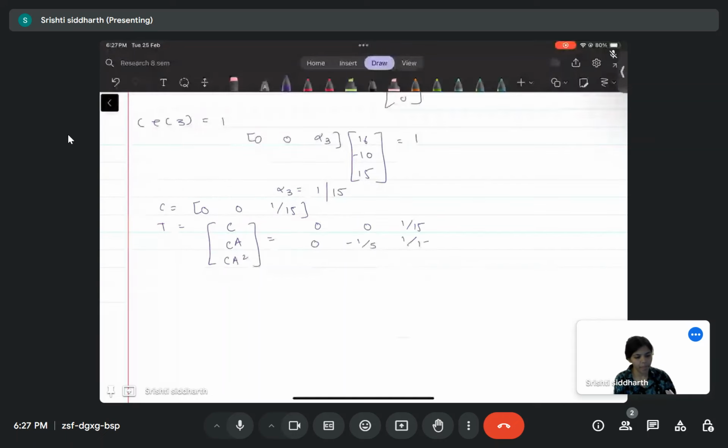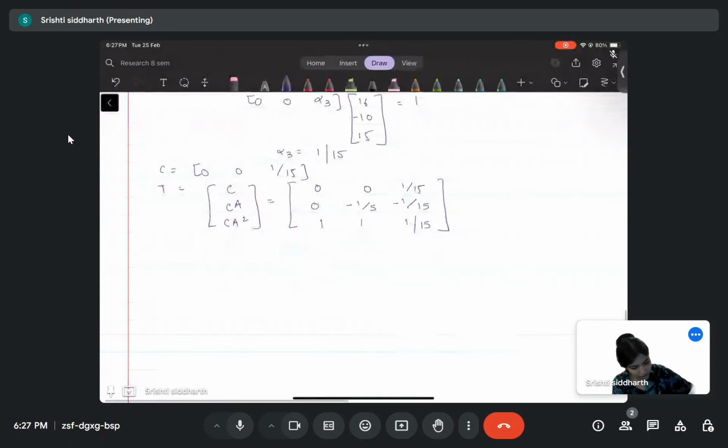Alright, so now we need the controllable canonical form. So we need AC and BC. So how can they be computed using the transformation matrix T and A? So we have y dot equals ACy plus BCu, and we have x dot equals Ax plus Bu, and the transformation y equals Tx.